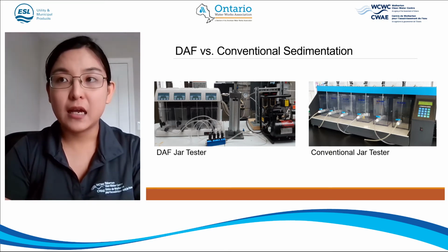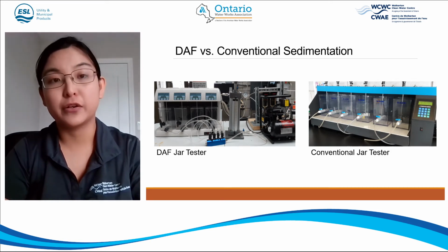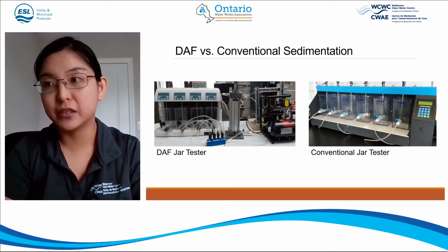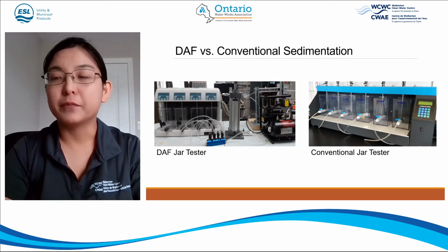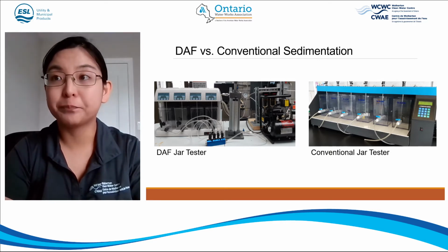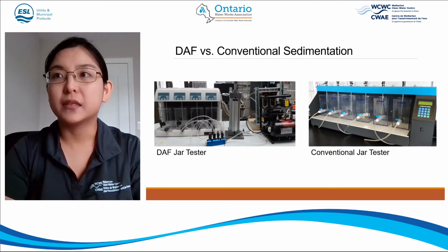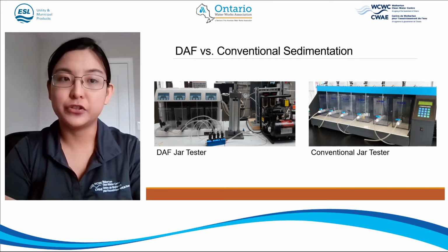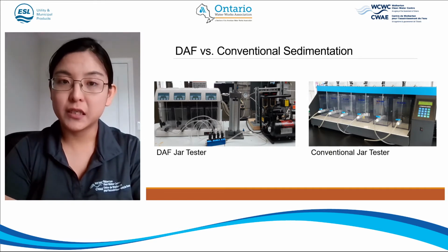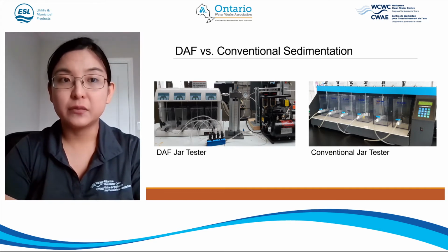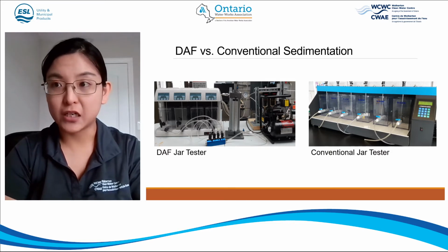And the main advantage of DAF compared to conventional sedimentation is that it has shorter start-up time and shorter flocculation time. And it's not as sensitive to low temperature. So that might be a bonus for this project. But again, we tested both technologies.